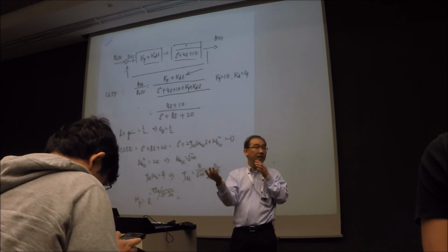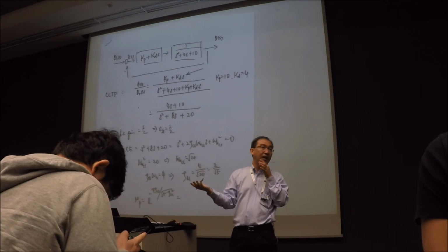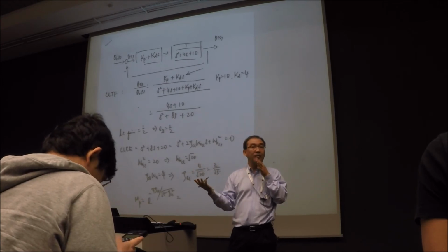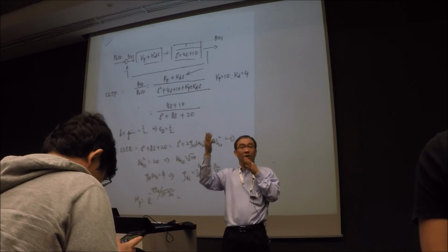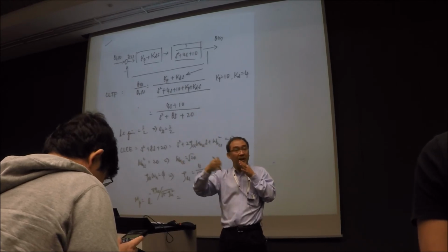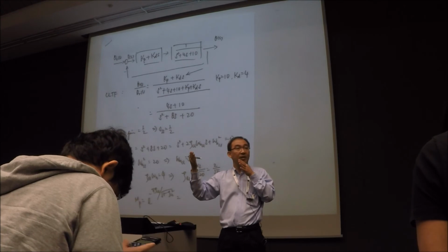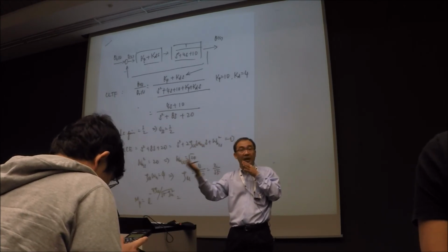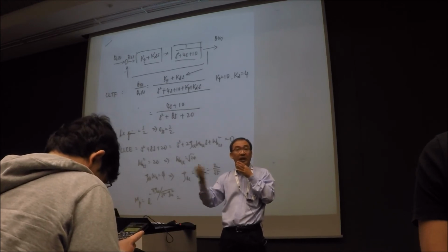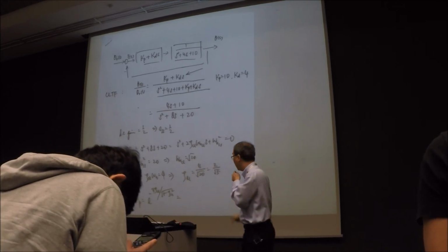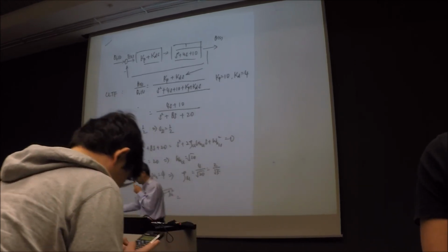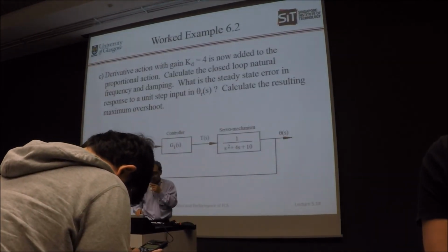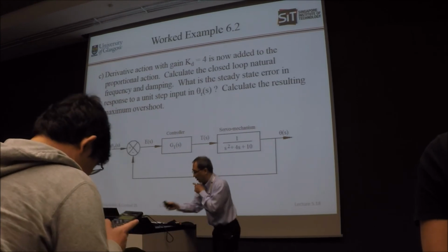They can say, okay, now I want my steady state error to be 0.2. Then what is my Kp value? You do know that your Kp relates to your steady state error. So if you have an ess of 0.2, you most likely can work out and straight away link to your Kp value. So that will be something that we will look into. Okay, alright, let's carry on.